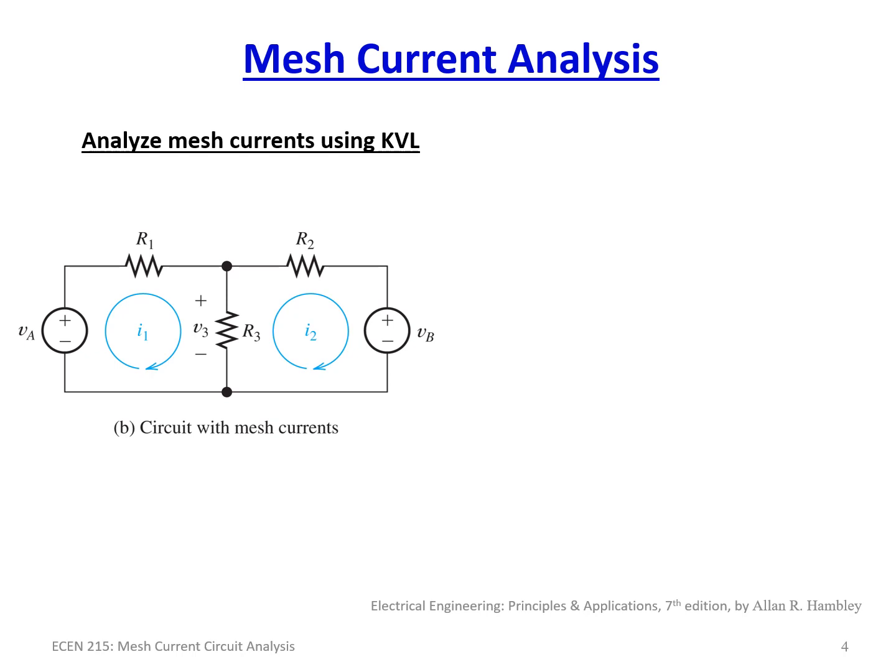So let's take a look at this particular problem right here. We've got R1, R2, I3, and we end up with 2 separate loops, loop 1 and loop 2. Let's write our equations for this. We're going to end up with 2 equations, so let's start with equation number 1. We're doing voltages, so remember, everything is going around following the arrow. If you enter a negative terminal, it's a negative voltage. And if you enter a resistor, you have to do it as positive based upon that direction of current.